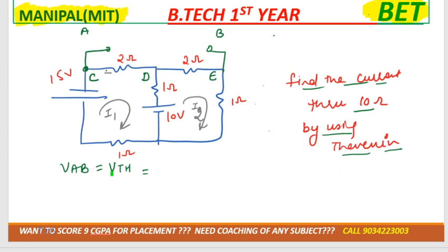Now for this, mark the signs positive, negative, positive, negative. So VTH would be how much? Minus 2I1 minus 2I2, and that is equal to VAB, that is VTH. Now how can we get the I1 and I2 values? By using mesh analysis equations.